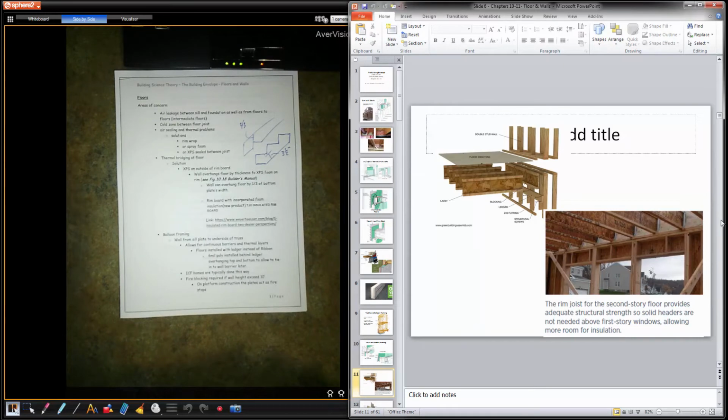So basically the lintel goes from one end of the building to the other end of the building, transferring the weight down through each stud. So pretty smart system, because if I have a massive lintel here, it's hard to build up insulation in that area. If I have a floor system, I can build that insulation all the way to wherever I would like.